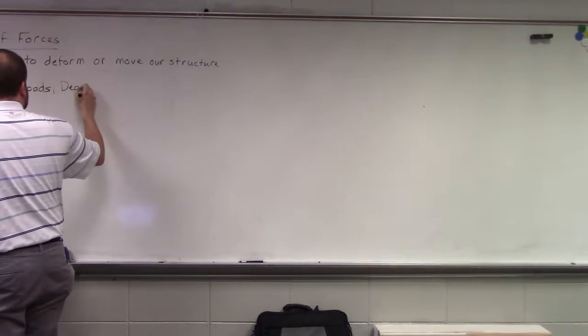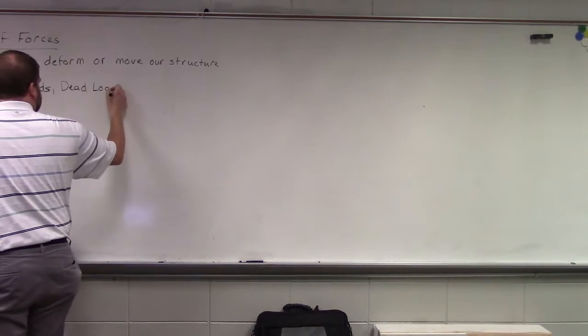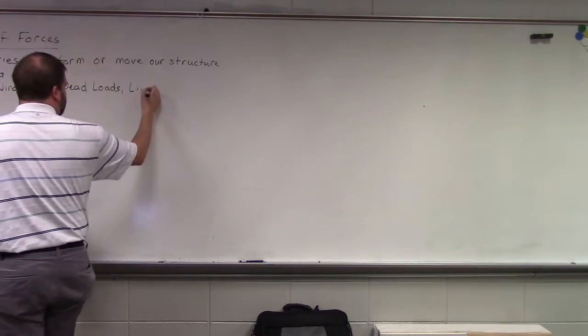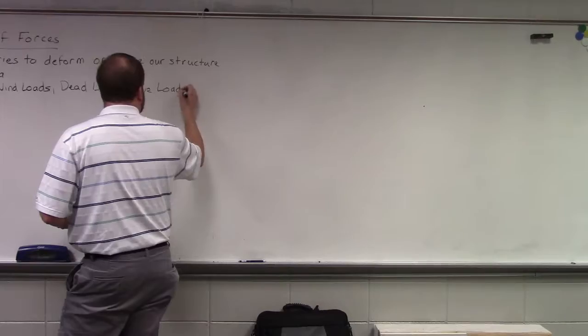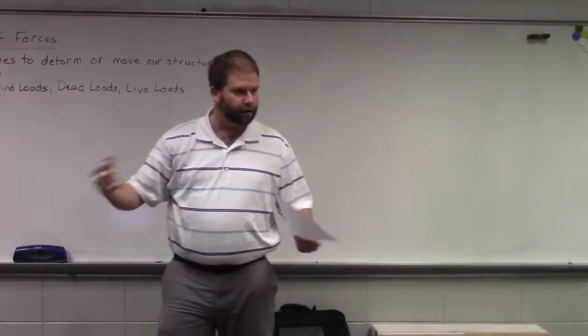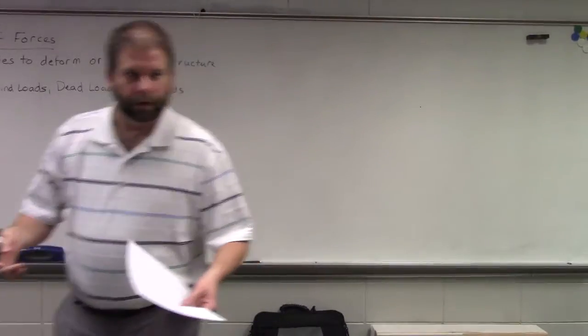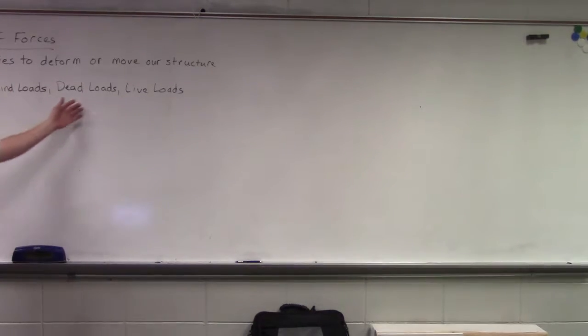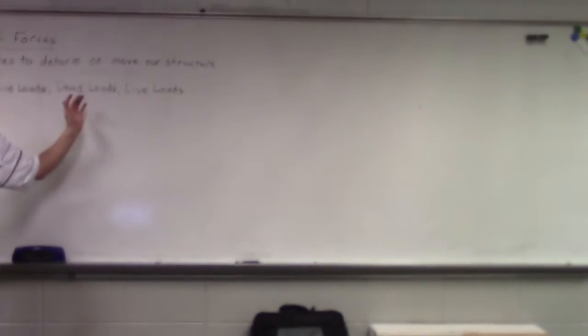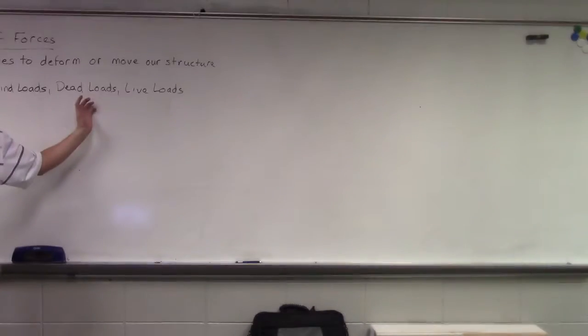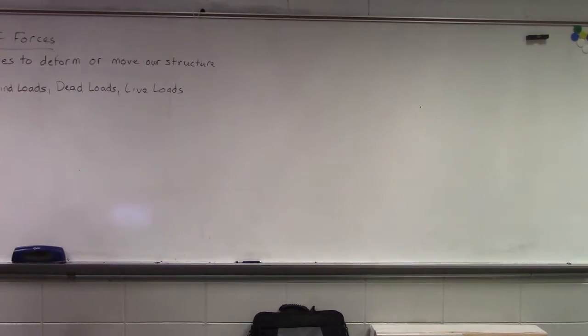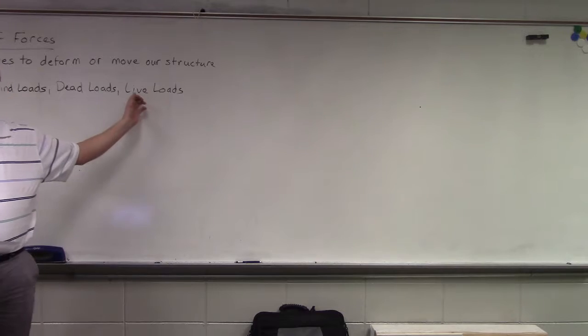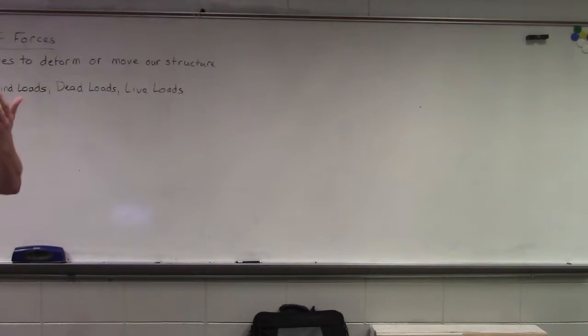Dead loads, yep. Live loads. And I know we talked about all of this stuff last semester too, and what's the difference between our dead loads and our live loads? Dead loads is structure, live loads is occupancy. Yep, dead loads is going to be our structures, okay? So these are things that are always going to be there, right? They're always going to be impacting our structure. Our live loads, or you may also hear them as transient loads, may change over time, okay?